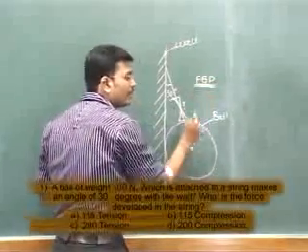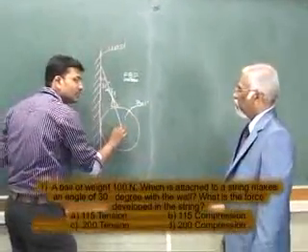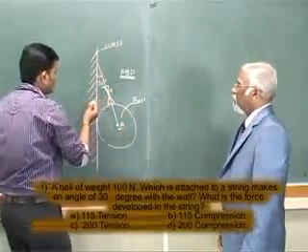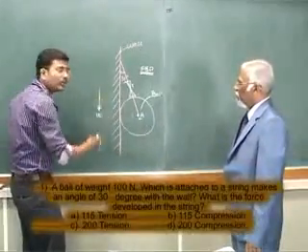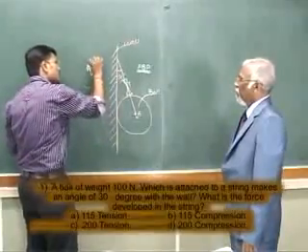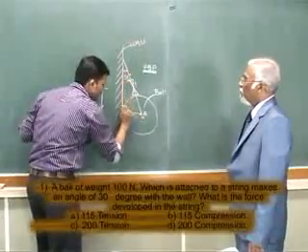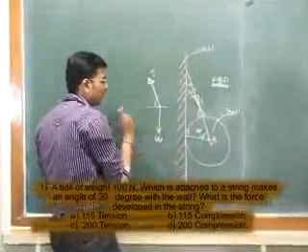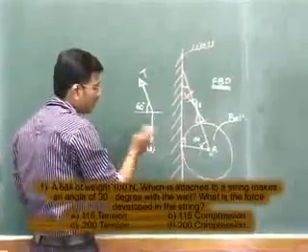this particular ball. Free body diagram is nothing but a diagram which shows forces acting at a point. So we have to draw the forces which are acting at point A, let's say. So the free body diagram for A will be the weight component which is acting in downward direction. Second will be this tensile force, let's say T, which makes an angle of, since this is 30, this will be 90, this will be 60 degrees. So 30, 60, 90, the addition will be 180. So this makes 60 degrees with horizontal.